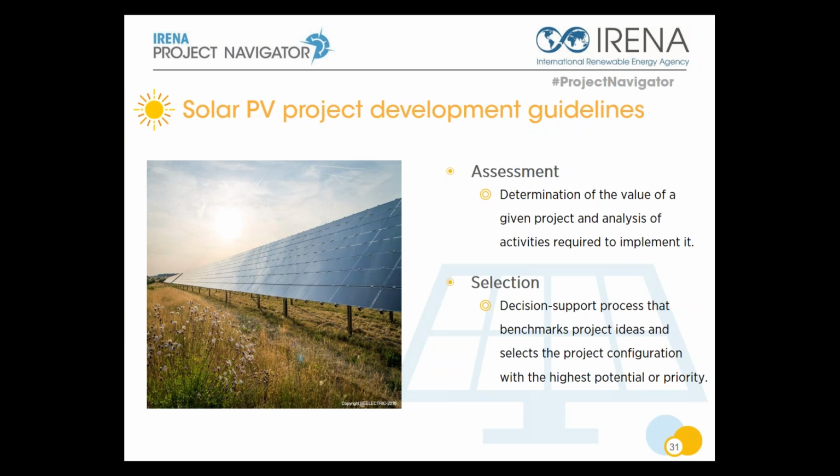Also very important are the site technical assessments. So here about, of course, meteo factors, but as well infrastructure factors. For example, do I have a substation? Do I have a means to connect to a grid? Very important. We have defined utility scale solar PV as a project connected to the grid. So do I have an available substation, or do I understand the process to connect to one? What is the distance? Often the distance to the substation will also increase the investment required for the project.